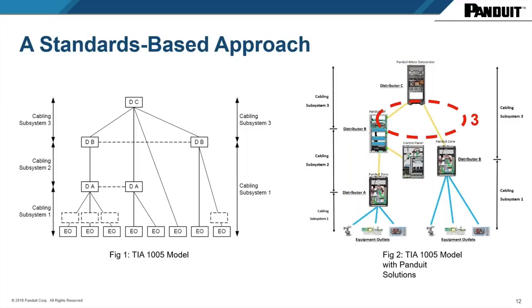Connectivity between these points also is something to worry about. So generally in a star topology, communicating from a control room to a distribution frame outside in the network, outside the factory systems, the distance between that micro data center and a distribution point on the floor can be a long distance. Generally, cabling between those two devices is fiber.